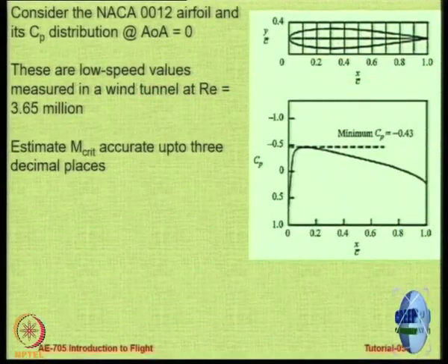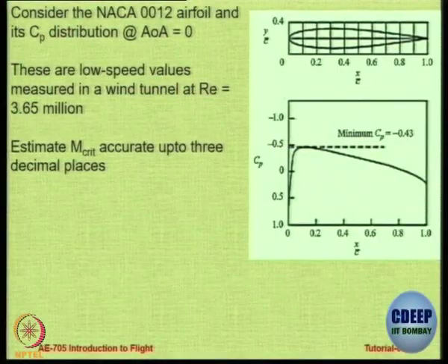Our job is to estimate the critical Mach number for this aerofoil accurate up to 3 decimal places. So how would you do that? Yes. Sir, my name is Vishnu. We will try to plot the Cp with the Mach number, and wherever it intersects with the universal line, we will consider that, or analytically also we can do it.